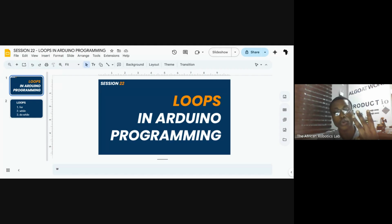You have one of the pins called MOSI, master out, slave in. You have another pin called MISO, master in, slave out. You have one other pin called serial clock, SCK. This time it's SCK, it's not SCL. For I2C, you have SCL, but for SPI, it's SCK. And then lastly, you have chip select or slave select. So you just connect those 4 pins from one microcontroller to the other, or to others, and then you have them communicate. So you've made some good progress.